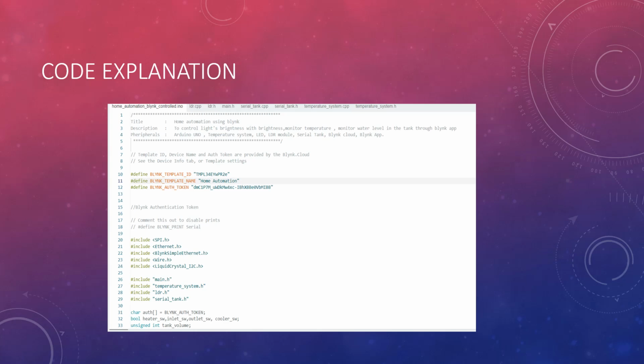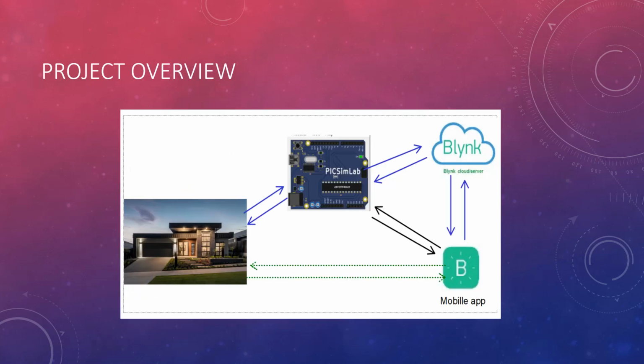The Arduino Uno is a widely used microcontroller board designed for prototyping and developing electronic projects. It serves as the central control in various embedded systems and DIY projects. It contains an ATmega328P, as we saw earlier. It has 14 digital I/O pins, six of which can be used as PWM. Then it contains six analog input pins. These pins can read analog signals from sensors.